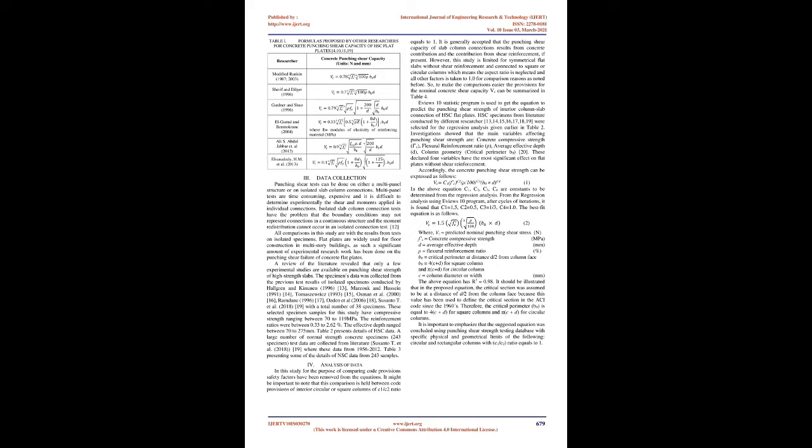The other important difference amongst codes is in the way they represent the effect of concrete compressive strength, f'c, on punching shear capacity. Generally, these codes express this effect in terms of f'c^N, where N varies from 1/2 in the ACI code to 1/3 in the European code. The further complication is the definition of the concrete compressive strength. The ACI and CSA codes use specified concrete strength f'c, while the European and Indian codes use characteristic strength fck. Punching shear provisions of current major codes are illustrated in Table 4.